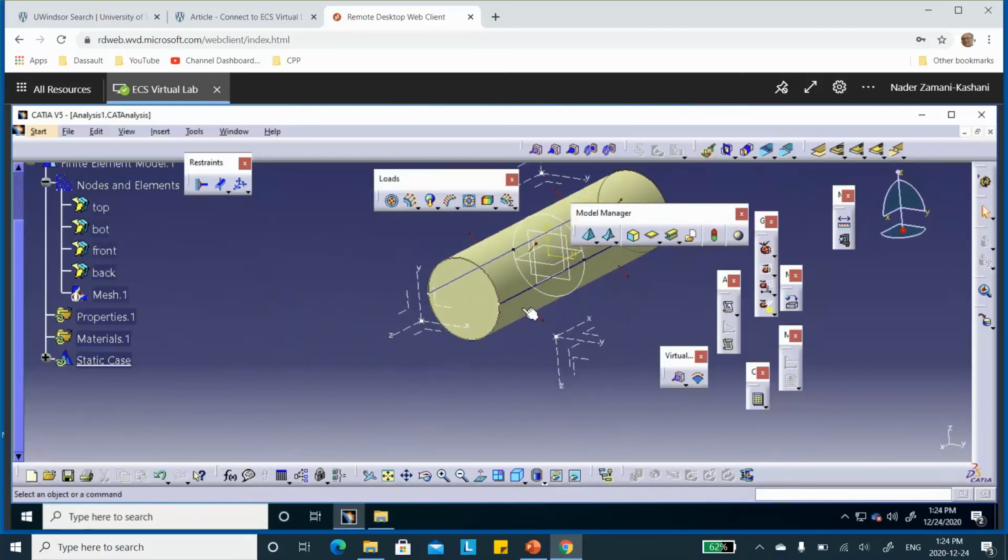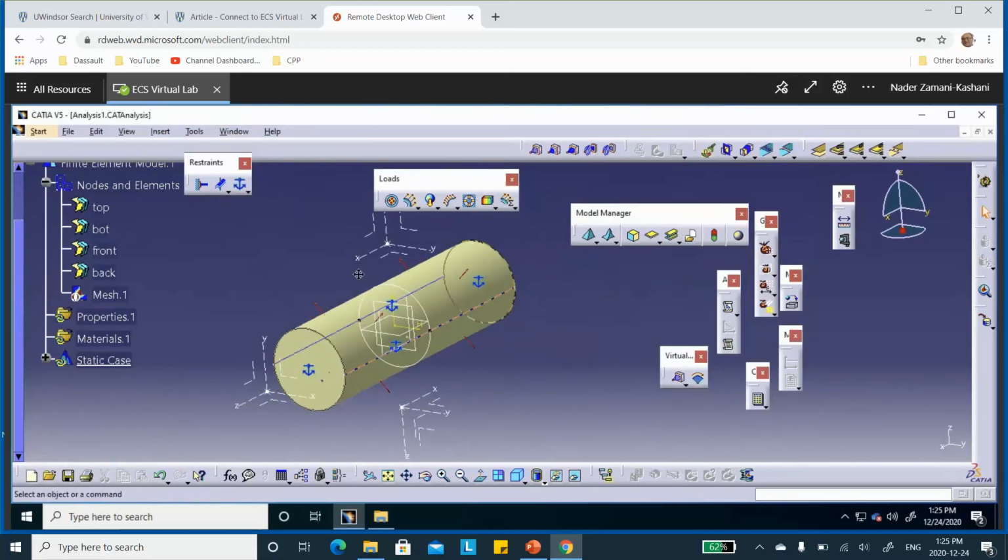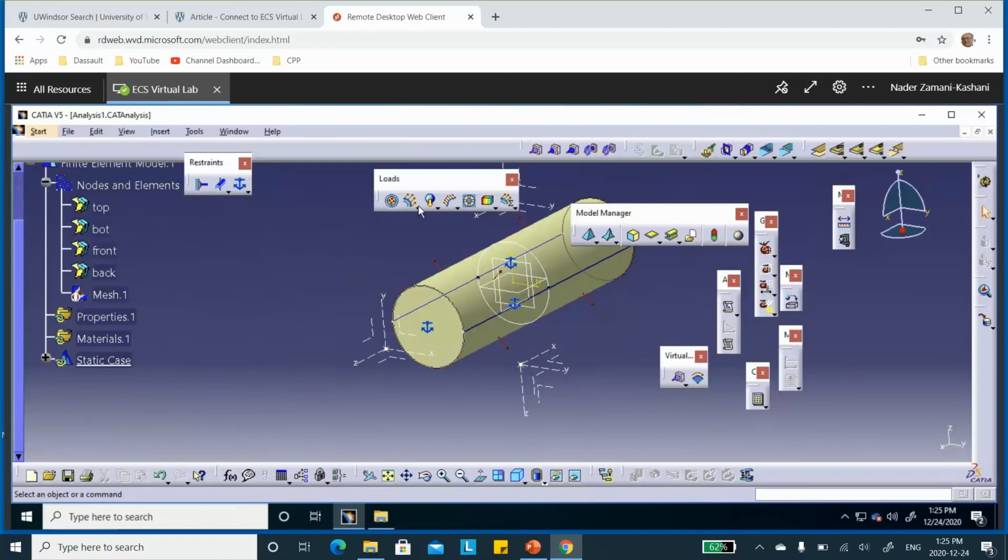Notice that these red arrows that you can see here, at the ends, have to do with the direction of the join, and I didn't join it here. Okay, good. So now we're going to impose the material. Well, actually, let's apply the isostatic restraint here, because this structure is going to be moving as a rigid body. We have to use the 1, 2, 3 rule or ask Catia to do it automatically for us. That's this isostatic restraint. It's going to put it on all these 4 pieces. I don't have to select anything. And finally, import material properties.